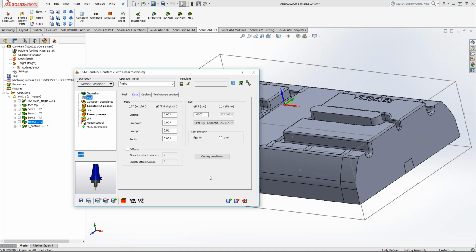I used the tool to burnish a flat floor, because it had to have a real good finish, and I think the spec on it was a 16 RA finish. I took it into QC to check the finish on what I got, and I ended up with like a 4.